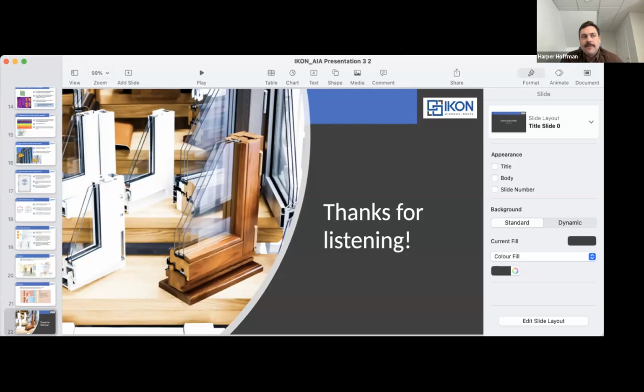They come in what's a titanium look. That's something you want to be clear on in your design process, to state and specify what color you want your warm edge spacers. We generally tell everybody to go black because your eye will not catch it. It'll kind of get lost in the IGU. That's usually the way to go. But a lot of people still use titanium, and it doesn't mean that your spacer is metal. It just means that it's finished in that look.